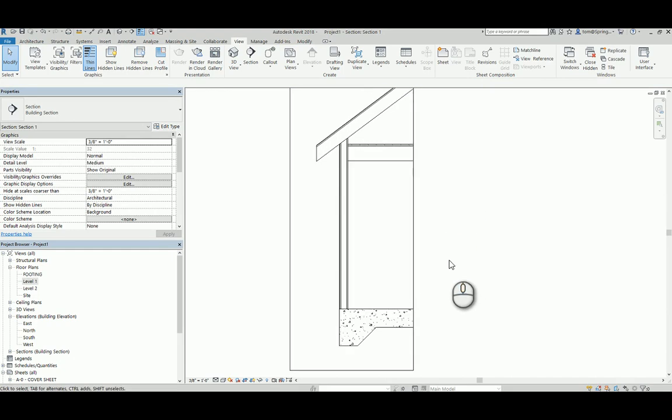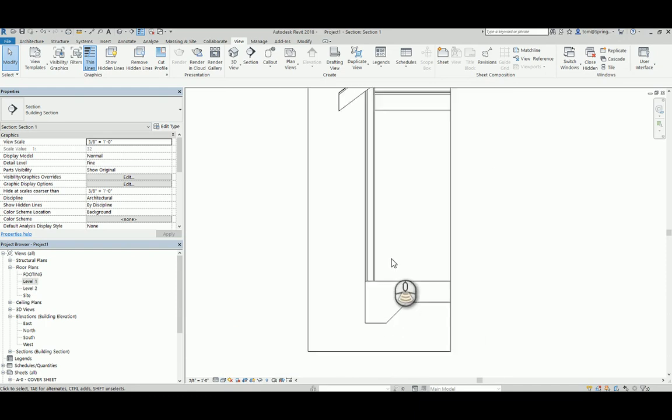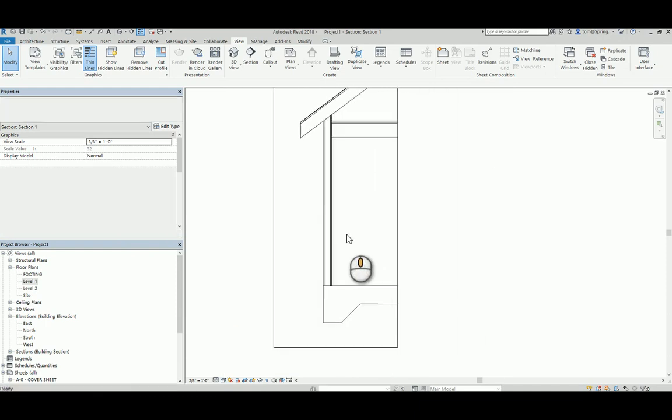So now, taking a look on page 5, I want to do a couple things here. First of all, the bottom looks good, and then looking over here, I'm seeing some good information, some good detail. So if I go to shaded, it shows me what's going on in that wall there. I'll leave it a hidden line here, and what I want to do now is put in some insulation. So putting in insulation is one of the easy things to do.